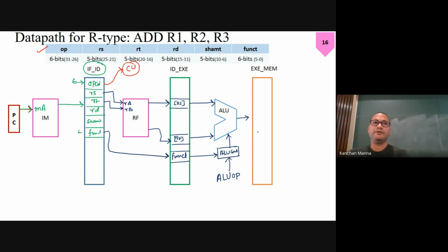So you are saying no. Why? Because this part is purely combinational, the ALU. If there is a change in the input, and because it is a pipeline, in this data path we have more than one instruction, then that value would immediately change here. Because of that, we first have to send this data to the register so that it can stabilize, right?